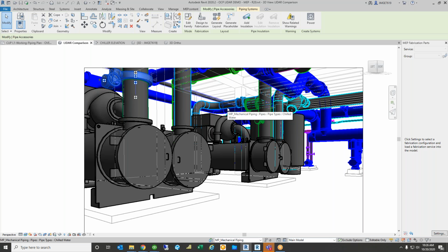When you get to 350, that's when you start saying, okay, if this is a black steel pipe, I've got to have it modeled as A53 black steel pipe so that I've got the correct IDs, ODs, etc. My flanges are all correct, so that if I say it's a class 150 flange, it's a class 150 flange dimension, and I cannot connect a class 150 flange to a class 300 flange. It doesn't work. Those are the additional types of information that you see in an LOD 350 model that you don't see in the lower LODs.